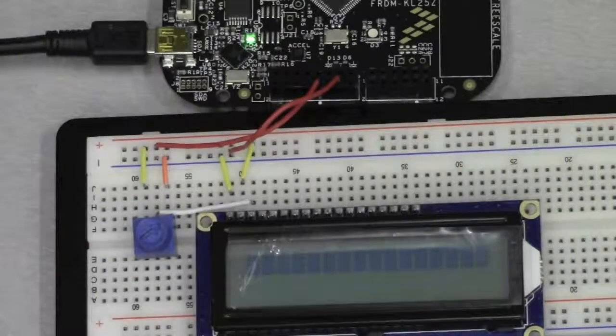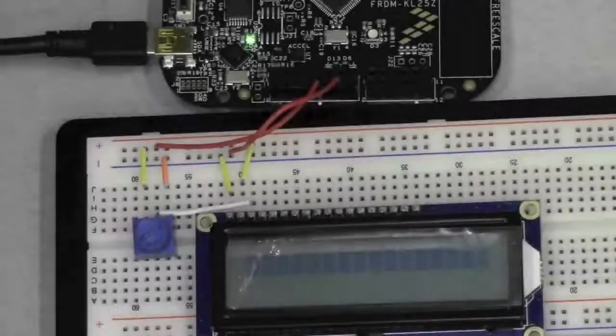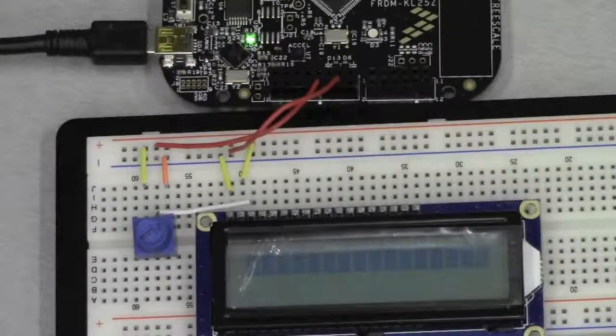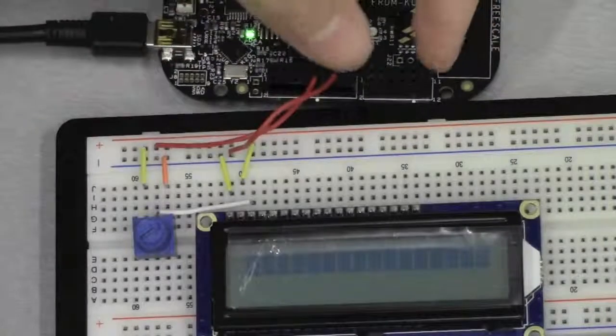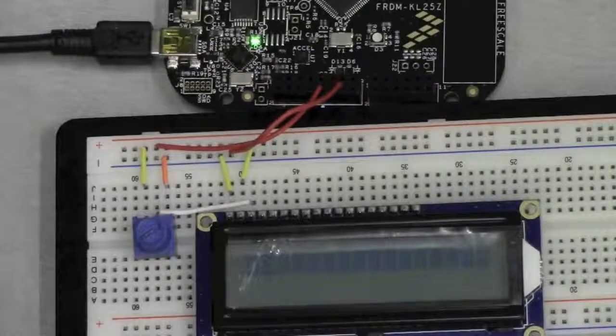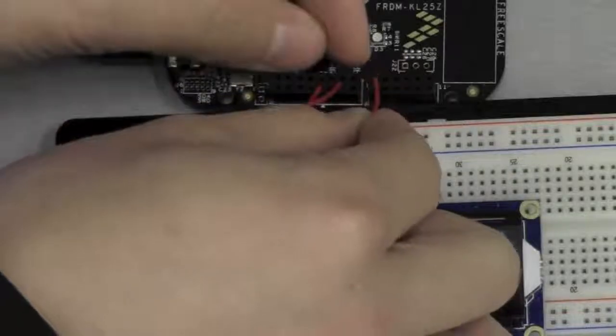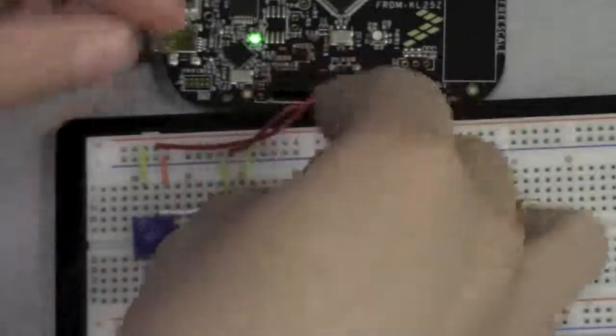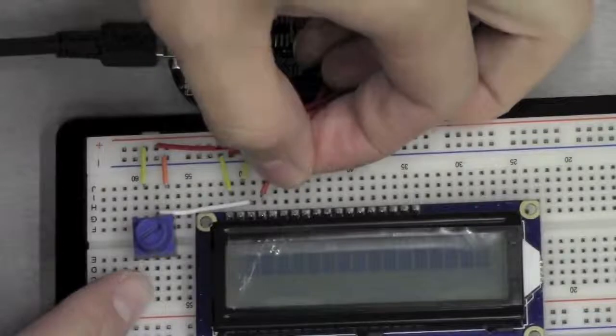All right. So now that we have the power on the LCD display, we need to connect the digital pins that will interface with this. The next one is read select, or RS, or register select. That's the 4th pin, and we're going to connect this to any arbitrary digital pin that we want. Because this LCD display uses 6 pins to operate, we're going to use the top left 6 right here for this tutorial. The first top pin is going to be for the register select, pin 4, which is right after V output.